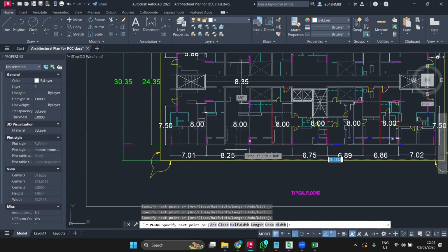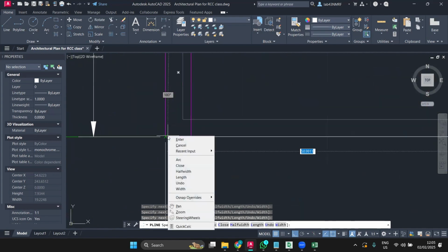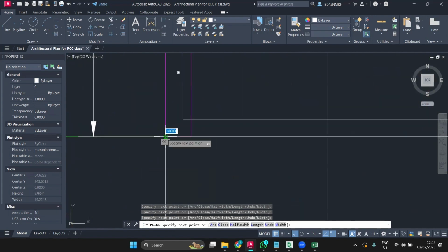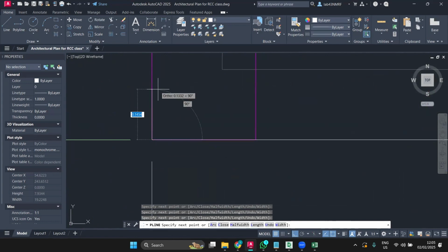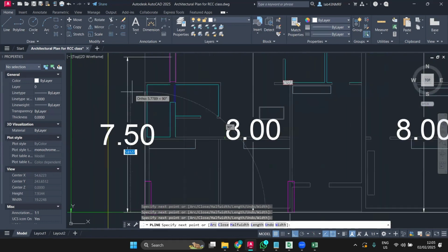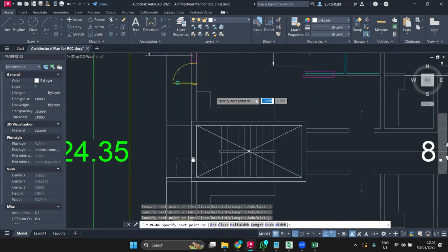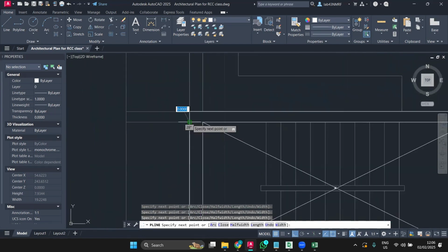Make it in one layer. Make it in one layer for your column, setting out the slab edges, even with the openings, even with the walls as well. All of them should be in one layer. Openings as well, because you do have bigger openings. I have seen so many openings; there is a shaft opening.